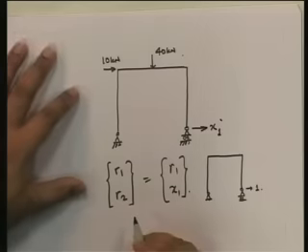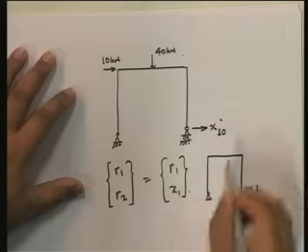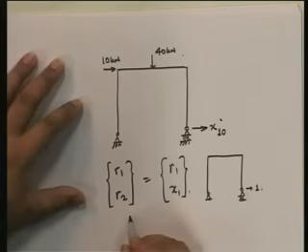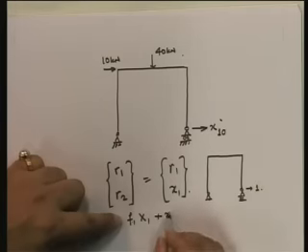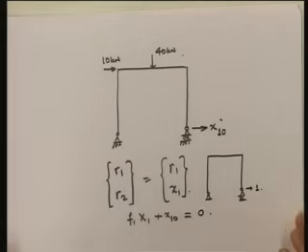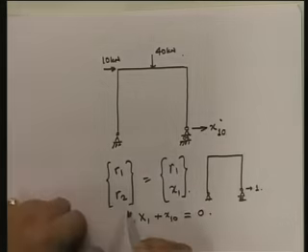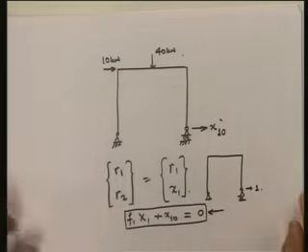So then we can say that this would be X1,0, and f1 X1, what is this? This is the displacement at this point due to X1 equal to 1. So then f1 into X1 is the displacement at this particular point, plus X1,0 is equal to 0, right? This is the compatibility condition that you would satisfy in the normal force method, right?